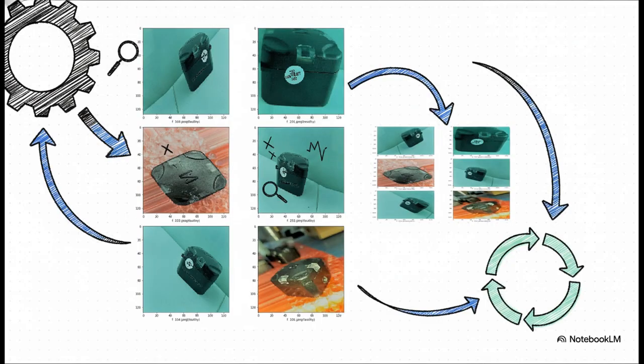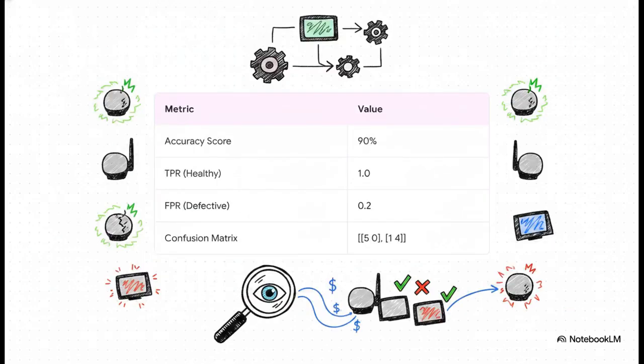But here's the catch. How do you train a digital inspector when your factory hardly ever makes broken items? Industrial datasets of faulty devices are usually tiny. To get around this, researchers used image data generators to clone and manipulate synthetic training images. They artificially added zooming, rotations, and translated angles. They were basically photoshopping realistic dents onto healthy products. This clever data augmentation let the model spot microscopic defects that a tired human on a crazy fast assembly line would definitely miss. And the real-world results?